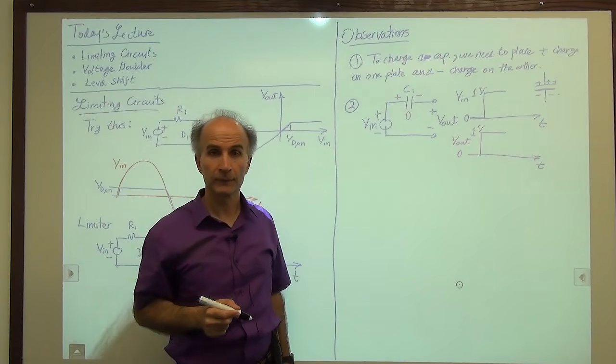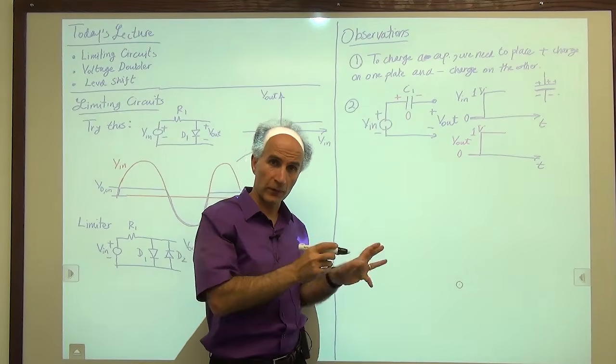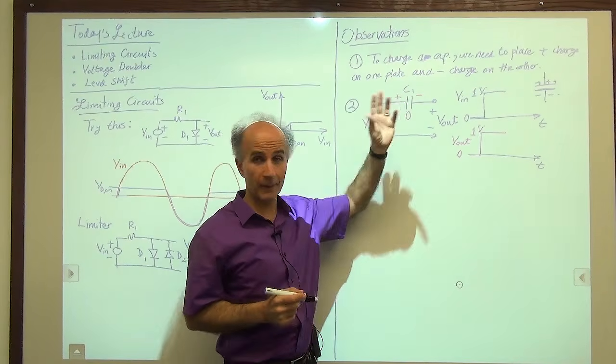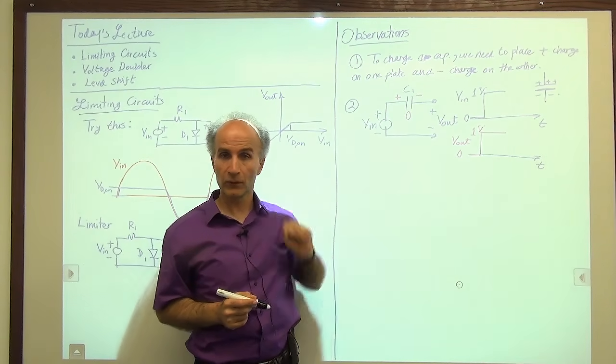Strange but true. So again, some students have difficulty when we have an open circuit here, an open circuit there. Sometimes we have a resistor here, sometimes we have a capacitor there. But it doesn't matter, there's no current through the device, so there's no voltage on the device.